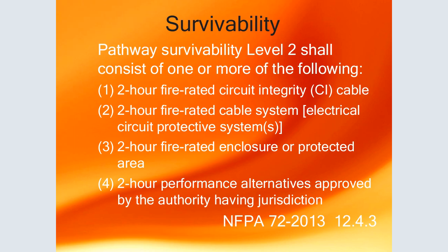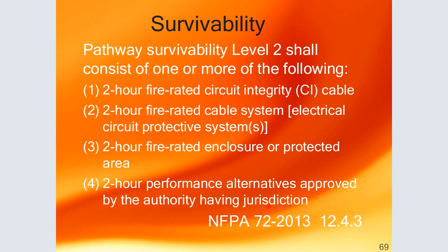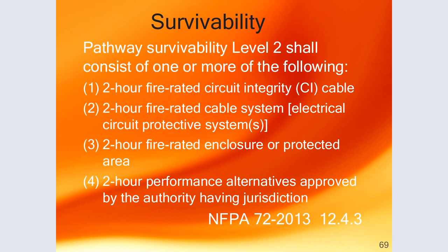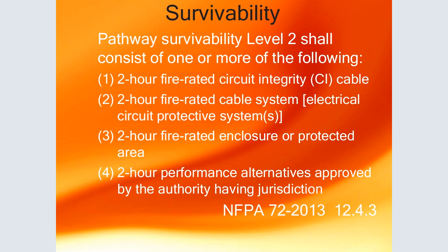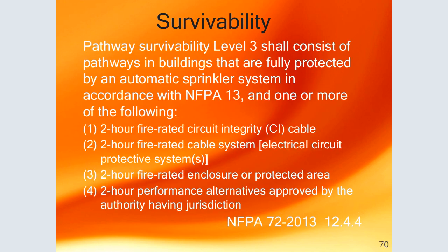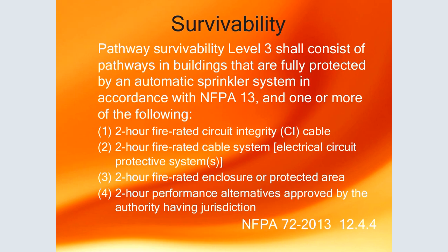Pathway survivability level 2 shall consist of one or more of the following: a 2-hour fire-rated circuit integrity cable, a 2-hour fire-rated cable system, an electrical circuit protective system, a 2-hour fire-rated enclosure or protected area, or a 2-hour performance alternative approved by the authority having jurisdiction.